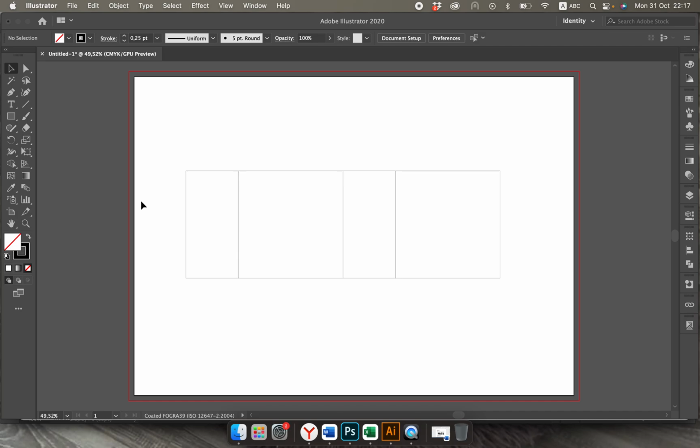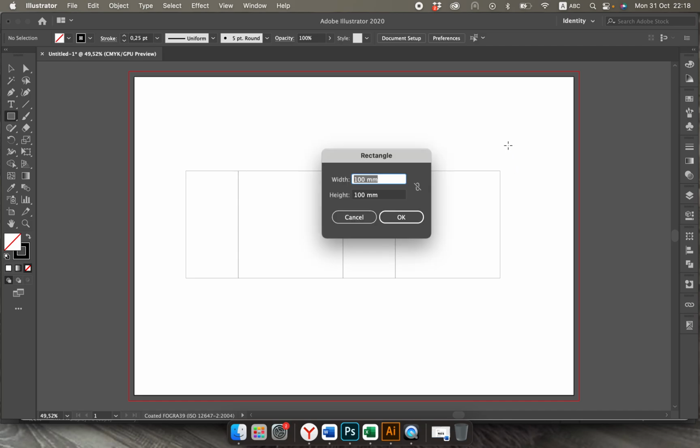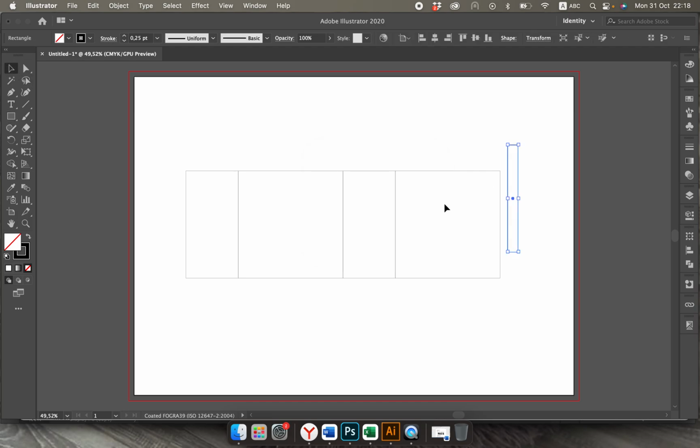The glue valve could be from 10 millimeters, about that size of the package, up to half a length or half a width of the side view of the package. Because we have a side view of about 50 millimeters, I will choose my glue valve around 10 millimeters by width. So again, click once on my artboard, 10 millimeters for width. I have this rectangle.